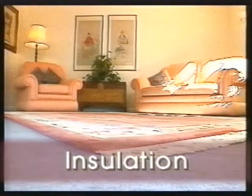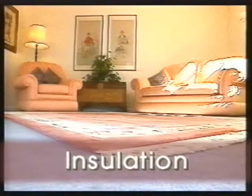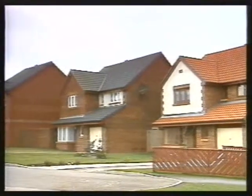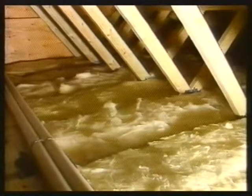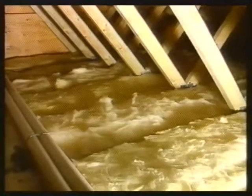The final topic to look at in this section is insulation. It's an obvious means of reducing heat loss. Newer properties tend to be designed with better standards of insulation, but older ones have some familiar problems. Lots of heat can be lost through the roof. It's a large area and should be insulated with one of the many materials available. Always make sure the layer is thick enough and also that there's no risk of fire and that it won't produce toxic fumes when it gets warm.